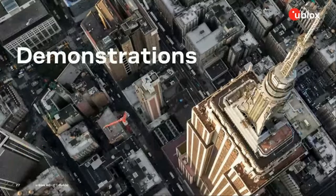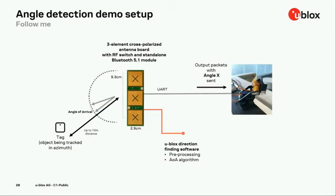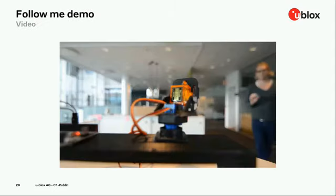Next, I would like to show you a few demonstrations in the form of videos that we shot using our products. The first video is a simple angle detection demo setup. It's a follow me application. We have a tag that moves inside the room, and the signals are being picked up by a 3-element antenna. The u-blox direction finding software U-Connect Locate performs the angle of arrival measurement, and out of the UART it goes to a rotor that is connected to a camera, and the camera follows the person that holds the tag inside the room. So if we can start playing the first video.